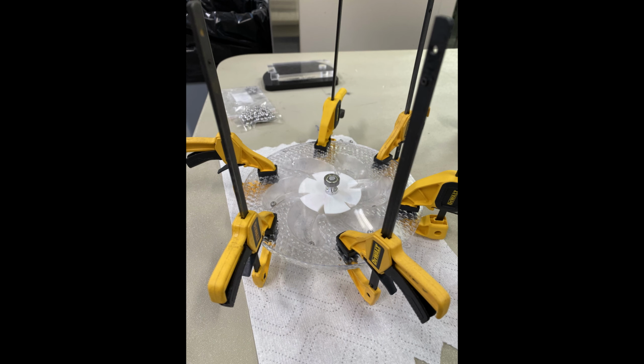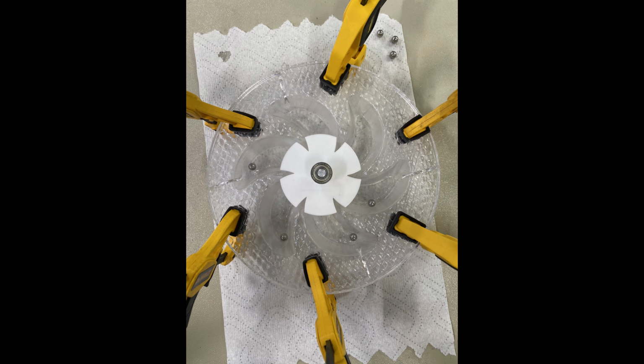The final step of my design project was to assemble all of the components. I started by gluing the 3D printed compartment divider to the upper interior of the plastic shell. After that glue dried, I put a 1/4-inch diameter ball bearing in each compartment and then glued the acrylic disc to the back of the vacuum-formed plastic shell, sealing in the ball bearings.